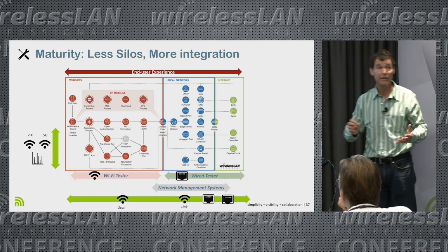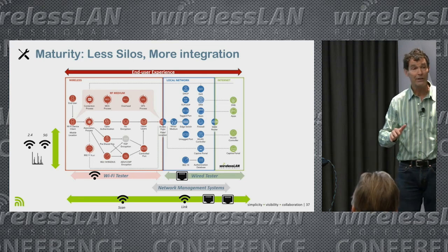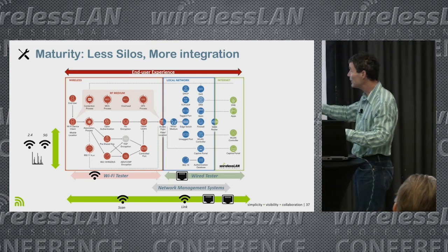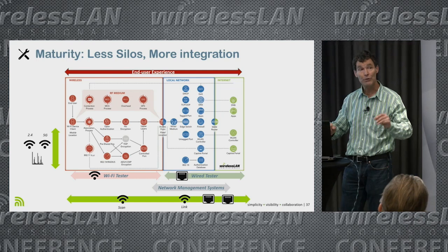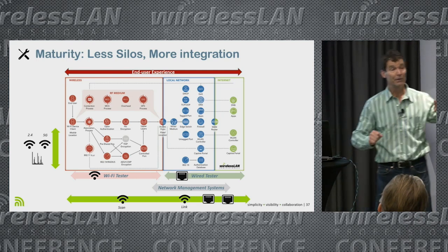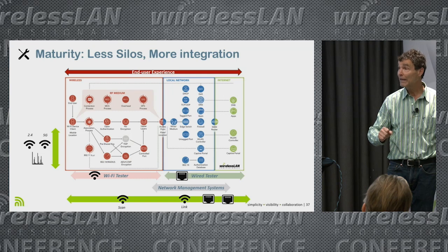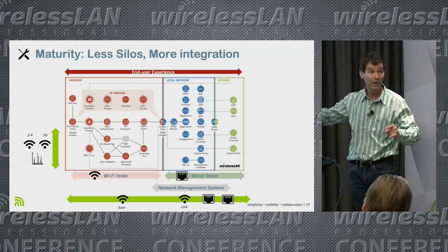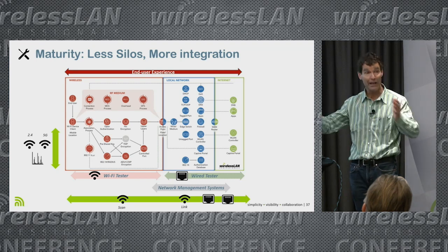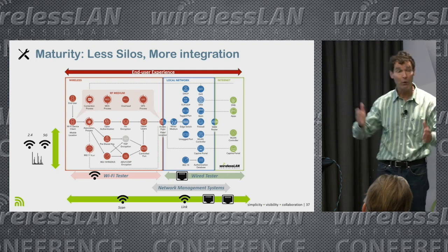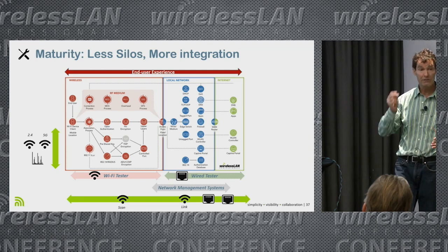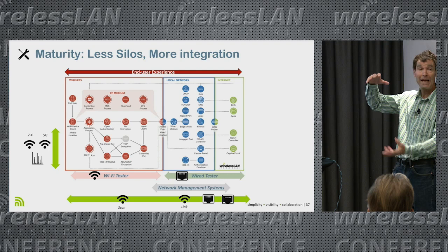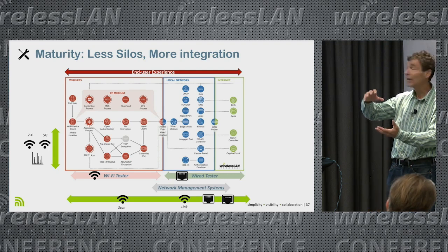And so on the tool vendors, and I'll speak about this agnostically, we're all trying to mature also, right? Our particular line, we're trying to do more integration. If you think about what you can do with 2 Wi-Fi radios in a product, right? Up until a year or two ago, you only had 1 radio in any given test product. Well, with 2 radios, in some cases, you're using it for scanning both bands at the same time, so that your survey has higher granularity as you're walking. You're basically getting those complete scan cycles every 2.5 seconds instead of every 5 seconds. Integration includes adding spectrum analysis. Some vendors are working that way.